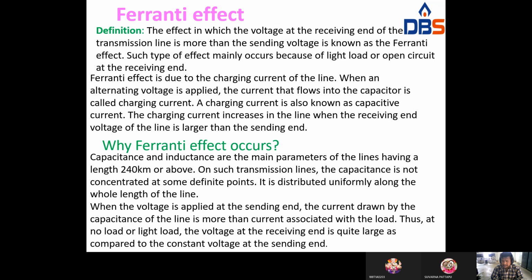Such an effect mainly occurs because of light load condition or open circuit condition. So at light load conditions or no load conditions, the receiving end voltage is greater than the sending end voltage. This effect is called the Ferranti effect. VR is greater than VS, right?